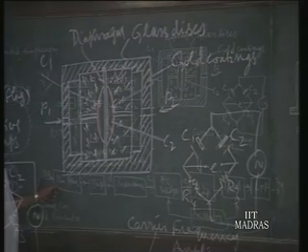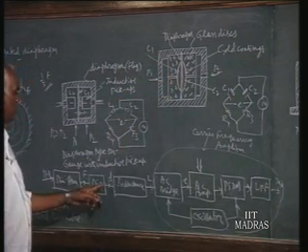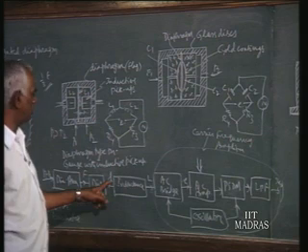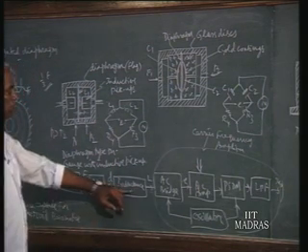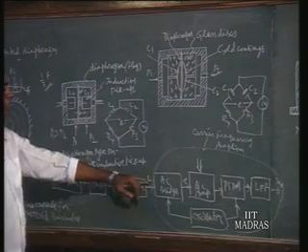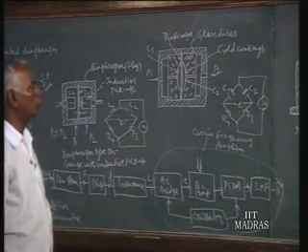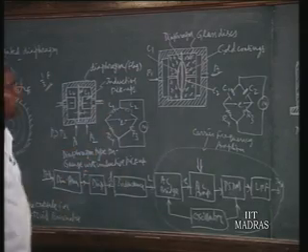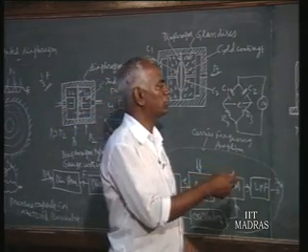More or less the same pressure difference produces force on the diaphragm, and the diaphragm again deforms by D. Here you will have capacitance in place of inductance, so you write C instead of L, and all the other things remain the same. You get the output signal. So this way the deformation can be sensed by using the capacitance principle into voltage also.